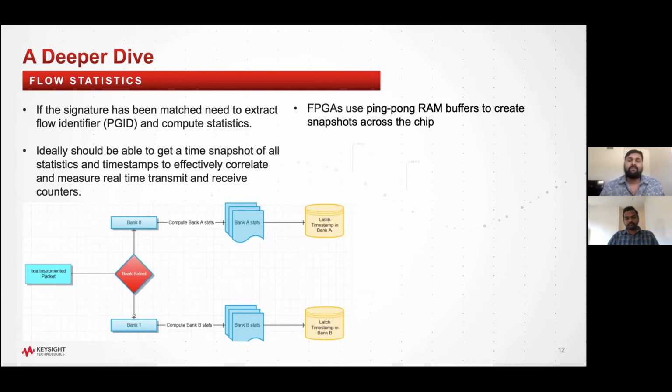Typically, in FPGA, we use a freeze pulse to get a snapshot. However, in P4, there is no synchronous mechanism to freeze stats simultaneously. We needed to get clever in our design and accept certain trade-offs in precision compared to FPGA.